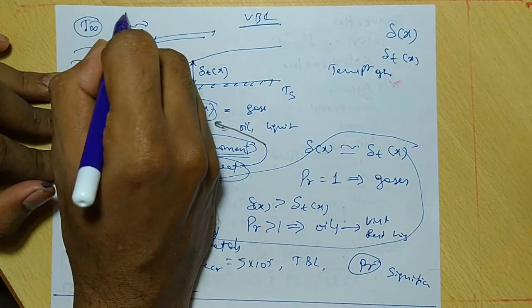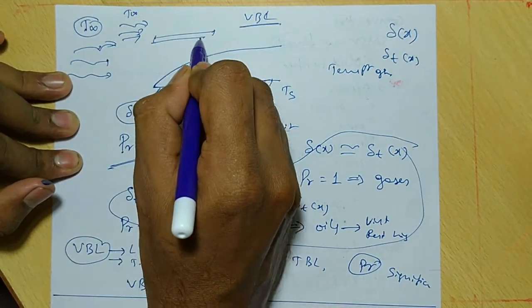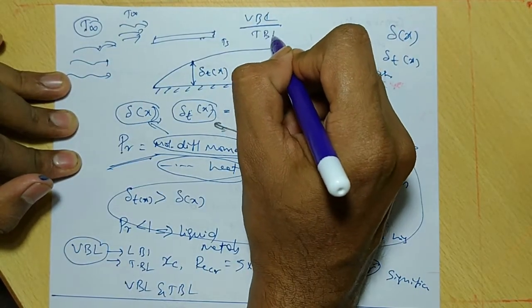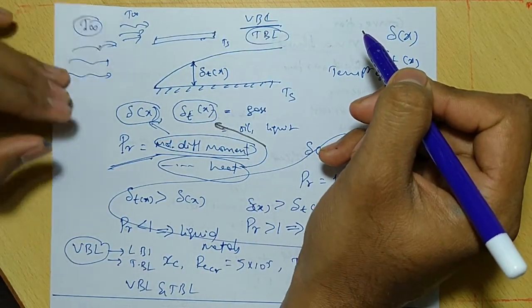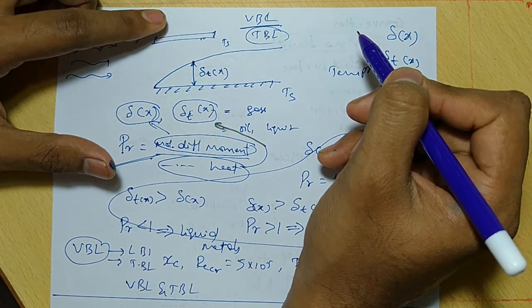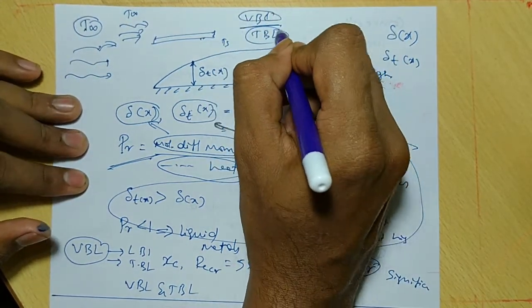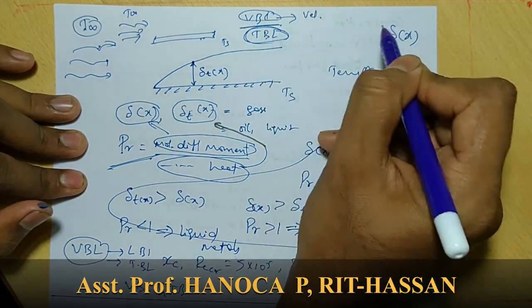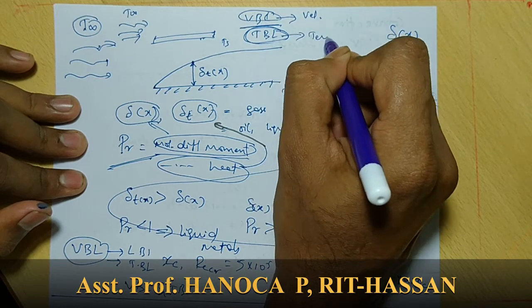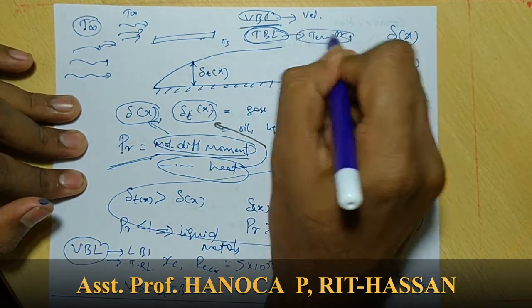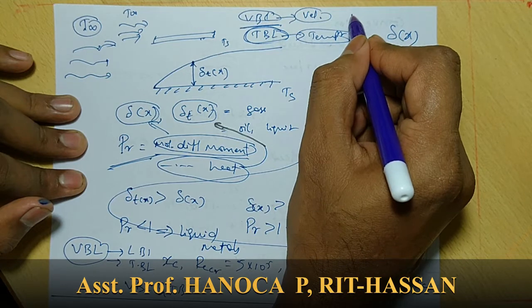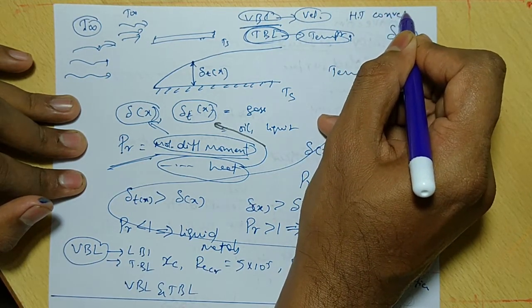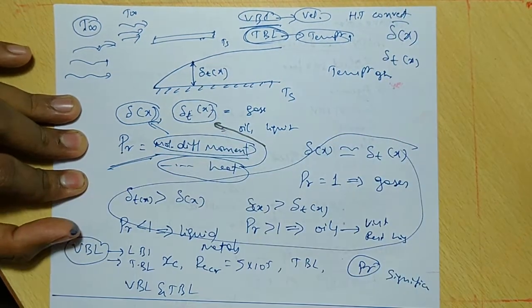If the fluid is at a different temperature from the surface, then automatically the thermal boundary layer (TBL) will also come into the picture. In the velocity boundary layer, there is a velocity gradient. In the thermal boundary layer, there will be temperature gradients. These things are very essential in calculating heat transfer, especially in the convection mode of heat transfer.